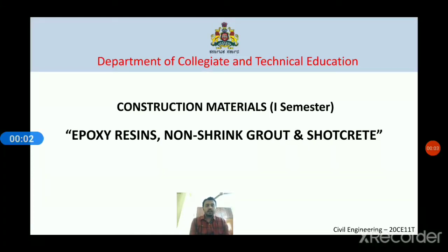Hello everyone. The topic in this video is epoxy resins, non-shrink grout and shotcrete. So what is epoxy resin? Epoxy resins are chemical mixtures containing the epoxy resin and hardener. It's also called an agent. Epoxy resin can be used for patchwork, used as an M-seal for filling cracks. We'll study what epoxy resin is and its applications in coming slides.